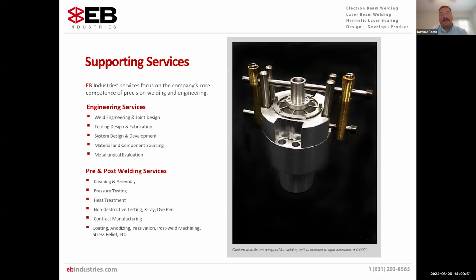A second thing is if you need to trap a vacuum with your weld. A lot of times we'll see aerospace valves where they'll have a cap component that is covering up a cavity, and part of the requirement of that cavity is to have a certain vacuum level. Being that most of our lasers are open air, you're just not going to get that vacuum within the cavity.